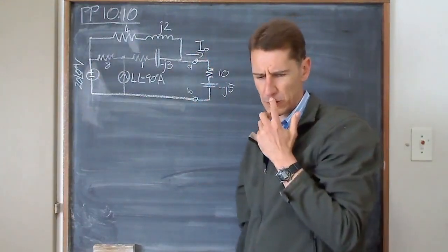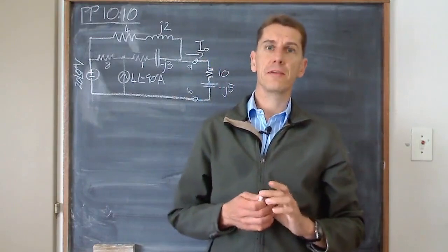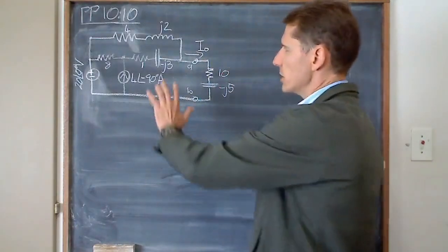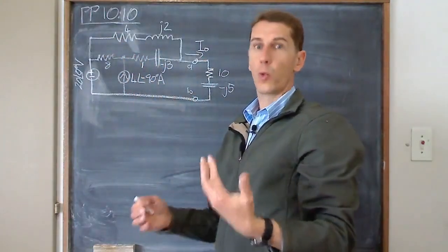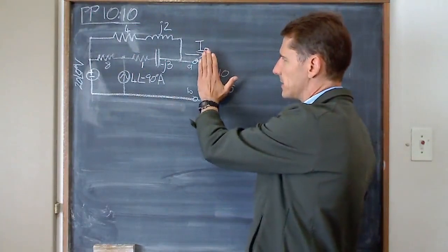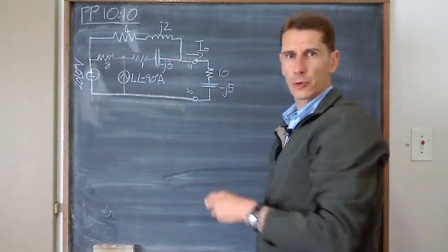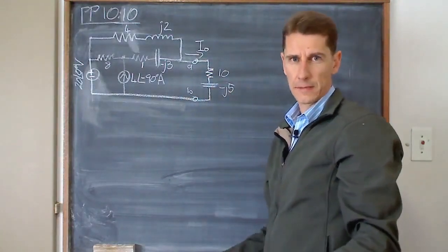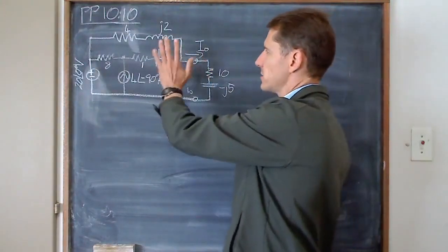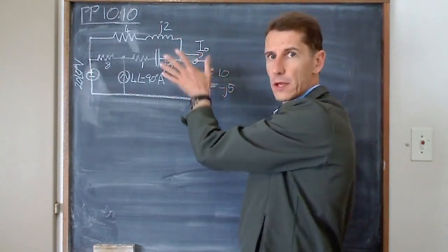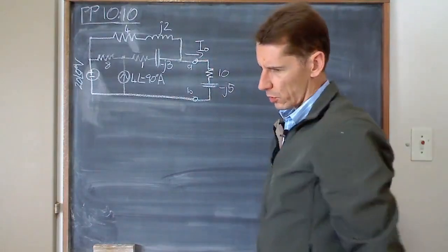And perhaps I should have mentioned this when we started with Thevenin and Norton. Remember, the whole purpose of a Thevenin or Norton equivalent is to simplify the complex circuit to just one source and one impedance, so that you can easily disconnect and connect different loads to that circuit and calculate what the load current or power or voltage is going to be. So for a big amplifier circuit, for example, you don't want the whole schematic. I just want to connect the speaker, and can I connect the speaker and what will the output be? So I want the equivalent circuit for all of this.